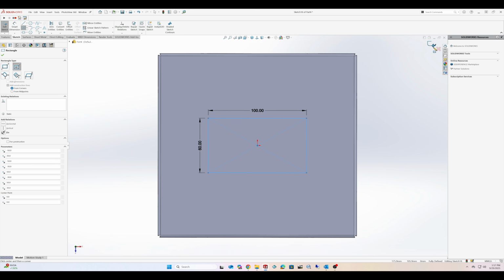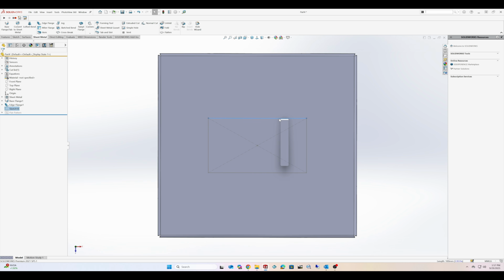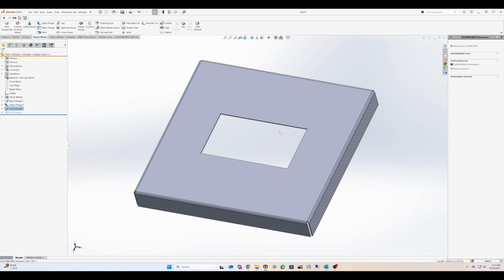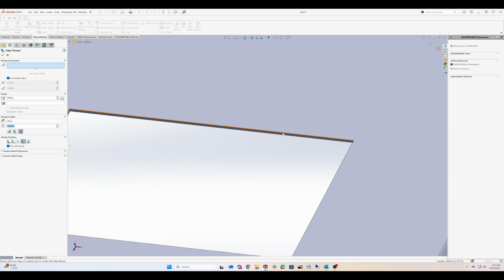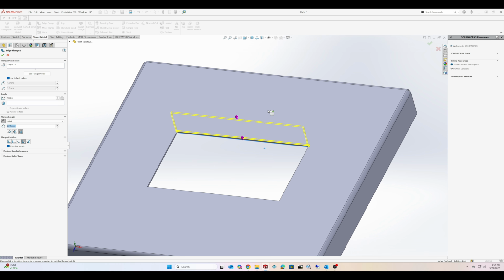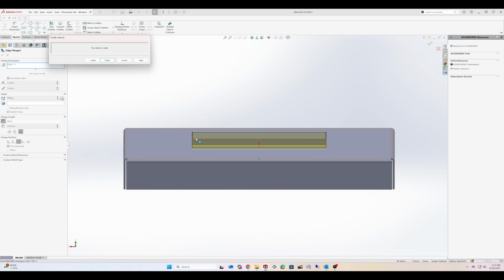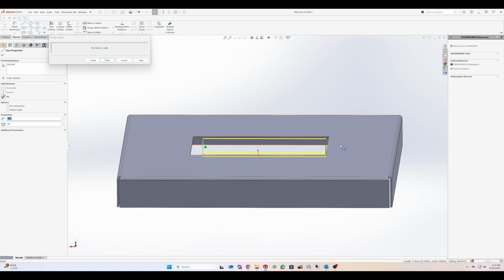When you can see these edges forming, you start to understand how the flat pattern will unfold and refold later. Now is the fun part, adding an internal bend to create a hand bend area. To do that, I sketch a rectangle, 60 by 100mm, and I cut it right out of the main face. This clears out the section where the hand bend will sit. It's always worth double checking your cut alignment here. It makes the downstream features much easier to manage.